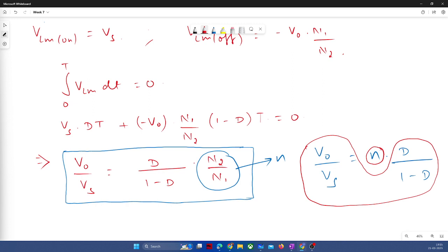But with the data sheet, you can estimate whether the converter is CCM or DCM. You will have certain parameters, you can compute and verify whether it is CCM. But if there is a very large change in the load, then sometimes we have to work in DCM. Yes, that is also another case. You are correct. If we design the control loop for CCM, it will have to work for DCM also. If we have variable load, then we will have to make it work as CCM as well as DCM control. But please suggest us.